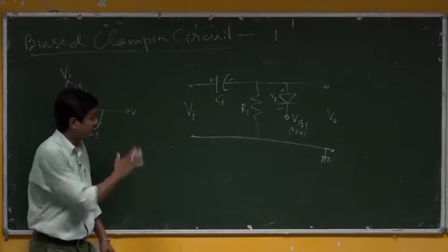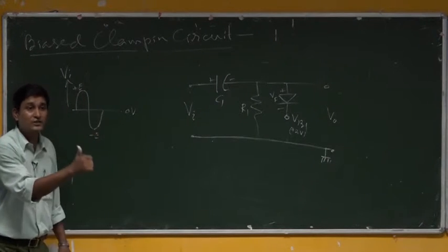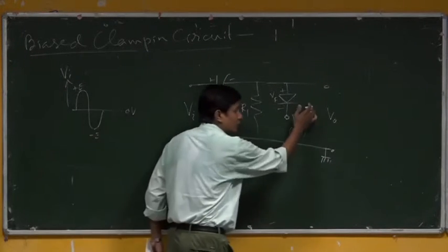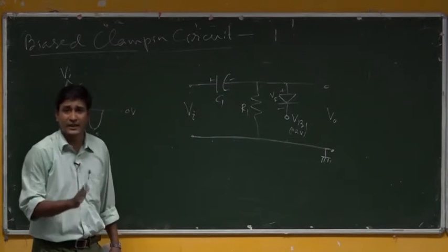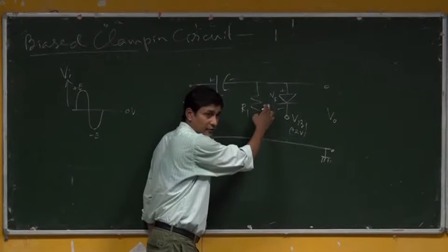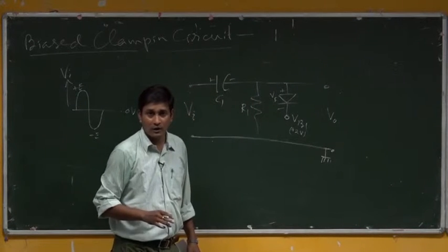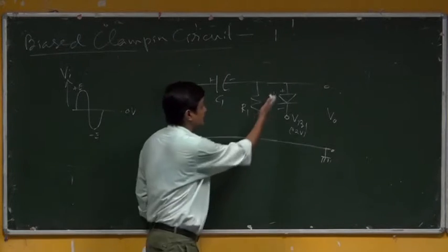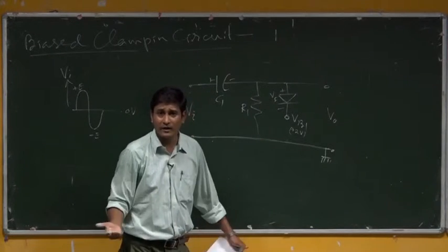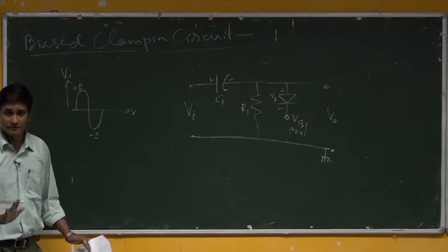Okay. So, in this circuit, what will be your approach? Maybe the signal has gone this way. You will try that if output voltage has come something for this diode forward biased, which will give Vf potential here across it, then what is the output? What is the other case? If the diode doesn't conduct, then it is open. So, no need to think about this complex part, remaining R and C only.